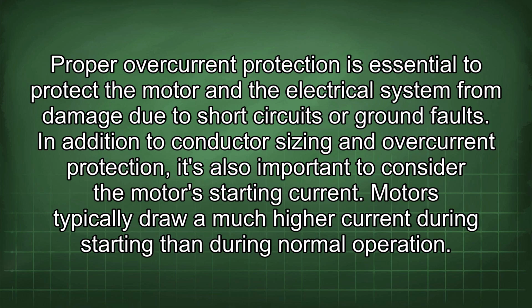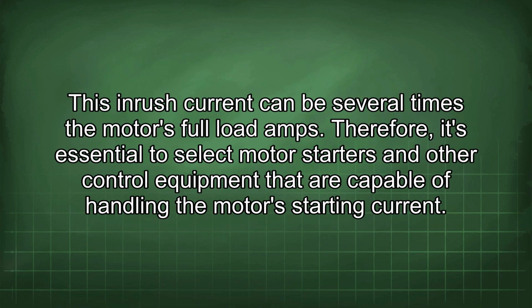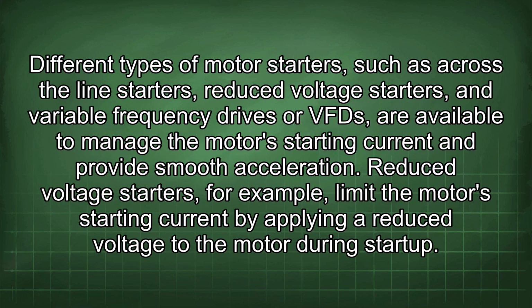In addition to conductor sizing and overcurrent protection, it's also important to consider the motor's starting current. Motors typically draw a much higher current during starting than during normal operation. This inrush current can be several times the motor's full load amps. Therefore, it's essential to select motor starters and other control equipment that are capable of handling the motor's starting current. Different types of motor starters, such as across-the-line starters, reduced voltage starters, and variable frequency drives or VFD, are available to manage the motor's starting current and provide smooth acceleration.